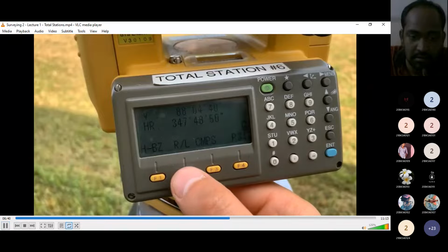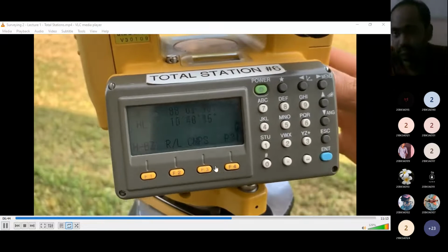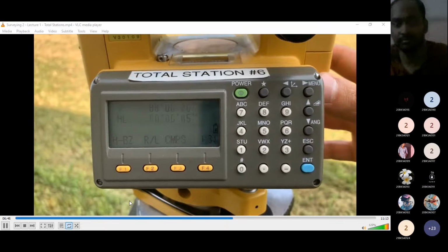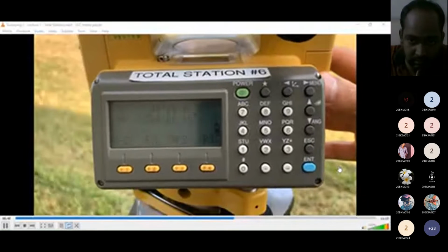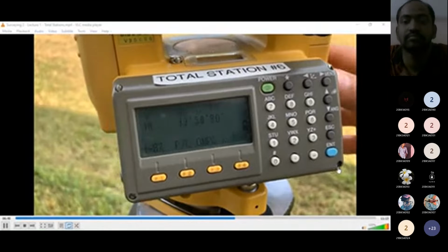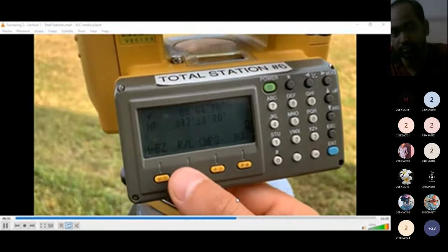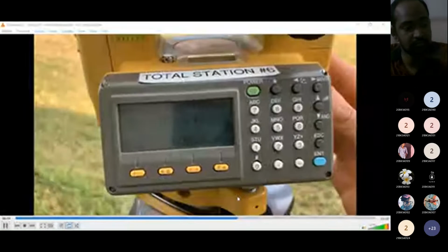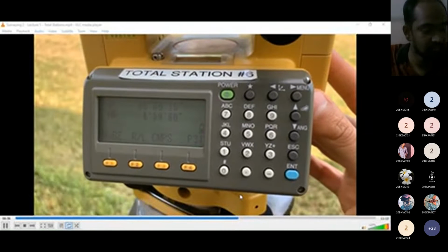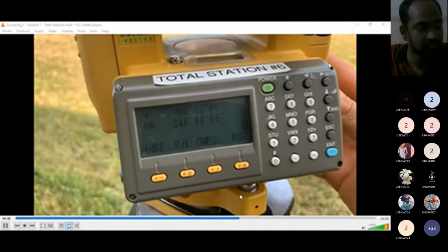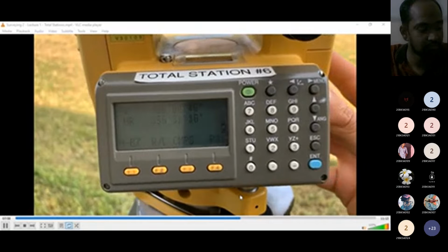from right to left or clockwise to counterclockwise. So if I push that, now rotating clockwise from R0 counts down from 360, and rotating counterclockwise counts up. If I push that again, it goes back to the other way. So at R0, now turning clockwise counts up, counterclockwise counts down from 360.